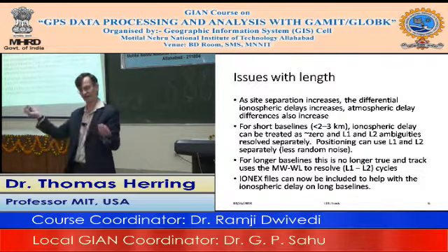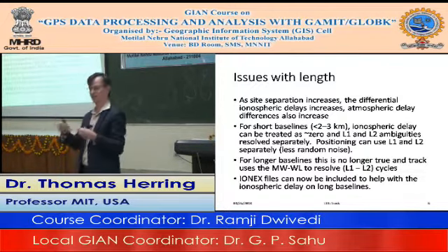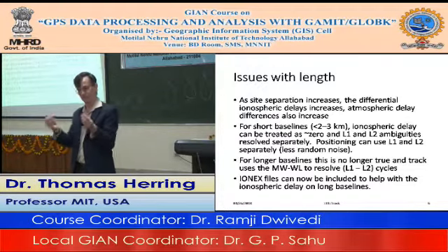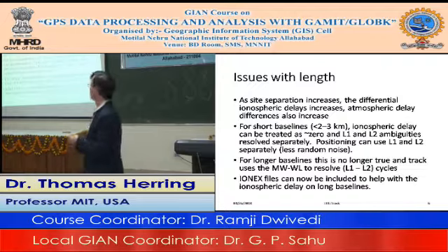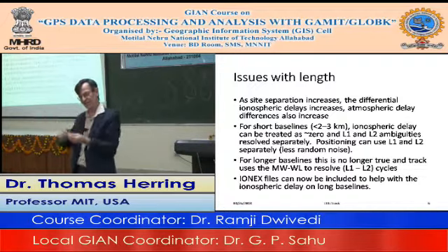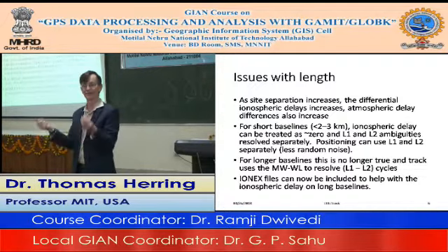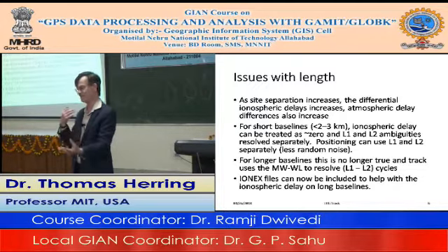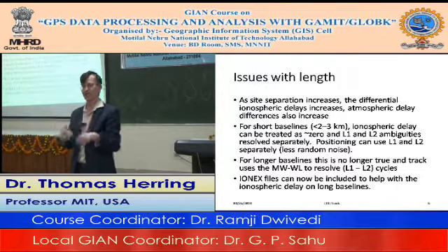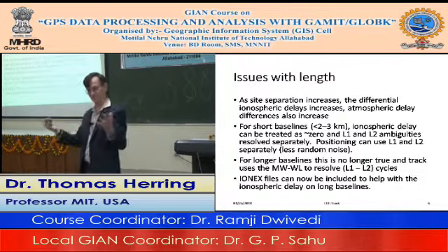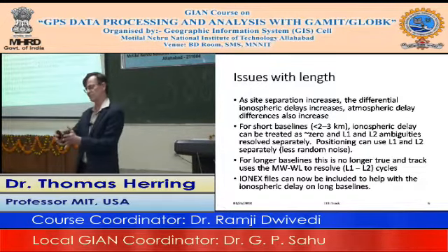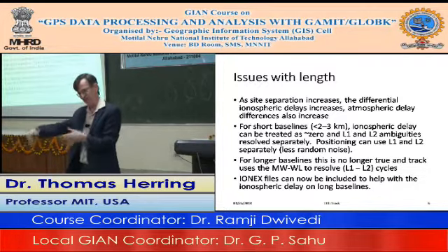And as you see, the total ionospheric delay is typically tens of meters. So it's a big amount, but for close stations, it tends to cancel out. So when you go to the longer baselines, we have to use this Melbourne-Wübbena wide lane using the pseudo range and the phase to be able to resolve that difference. And that's a noisier process. And so the longer they get, the noisier it is. And because it's a noisy process, the more data you can have, the better.